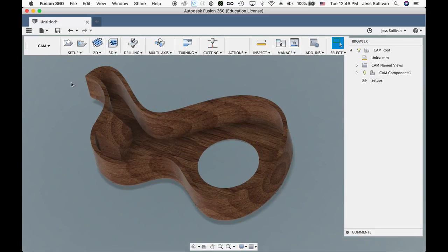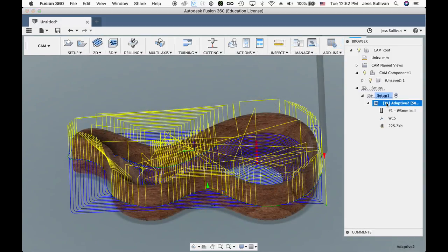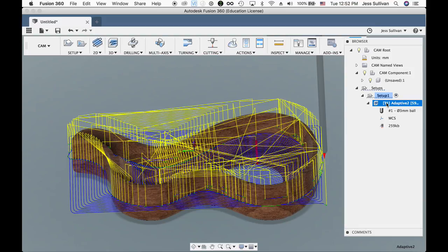We will cover CNC, or Computer Numerical Control Milling. CNC machines are subtractive in that they remove material from existing stock with a small router. While this is the opposite process of additive 3D printers, they work in a very similar way. Instead of slicing a model into G-code for 3D printing, which is a form of numerical control code, we will process a toolpath into a derivative of G-code specific to the CNC machine we are going to use.